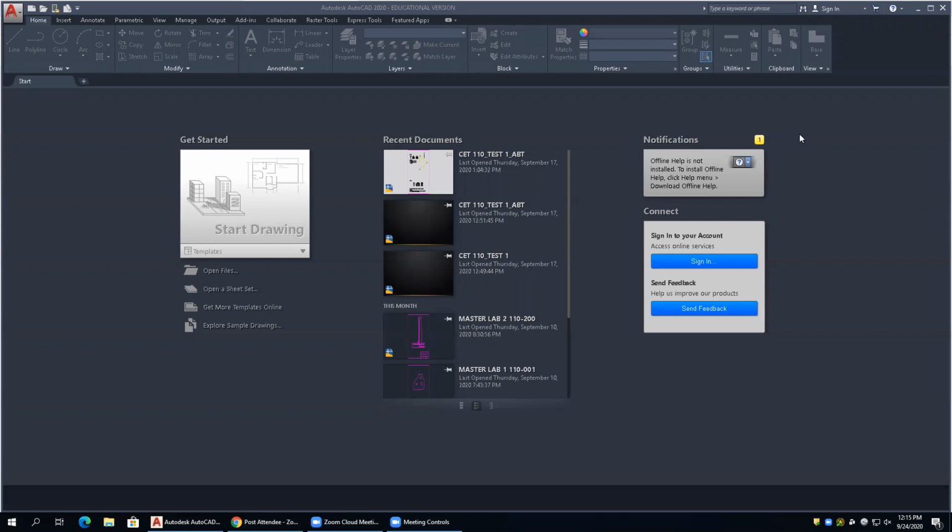and then we'll look at object properties. Object properties mimic layer properties. In other words, there is an object color and a layer color. You can't have two things going on at one time, so one will override the other, as we'll see in a minute. And then the other thing we're going to try to do is take a look at text today. Text is not a really hard concept. If I don't finish that today, I may finish that on Tuesday with you. All right, so let's take a look at layers.